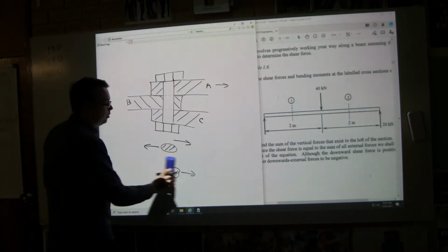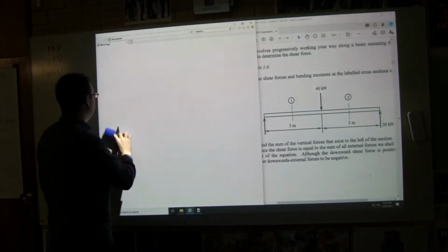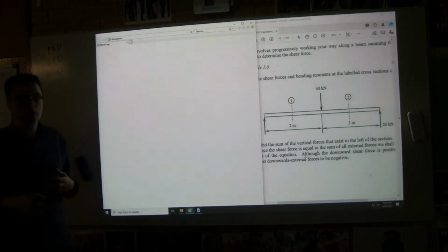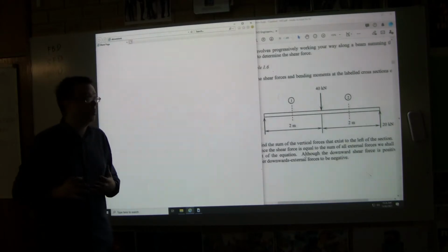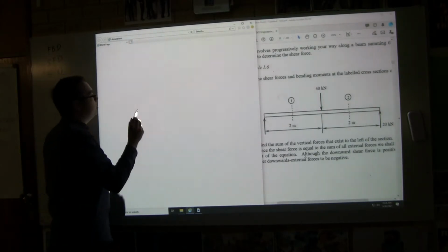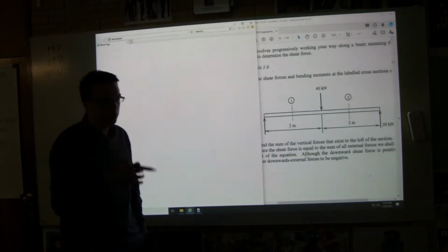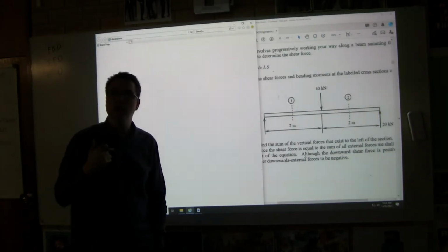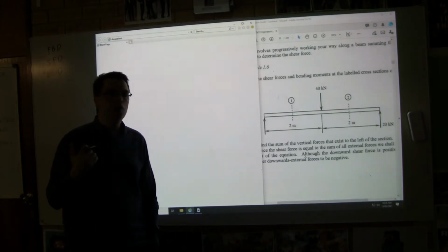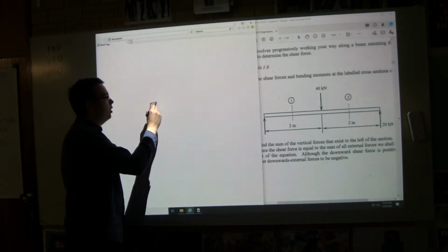Now that applies for beams as well. Generally, that's not a huge design consideration for concrete beams, for example, or steel beams. Shear is usually not the main consideration. There are times though where we are concerned, and what happens is if we have a big concrete slab, especially in places like garages, in car parks, you might have columns spaced throughout the middle to support the concrete slab.